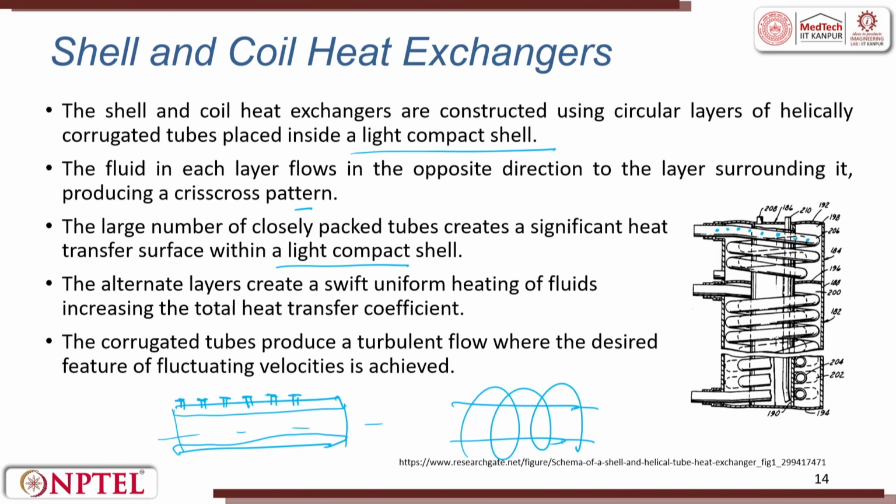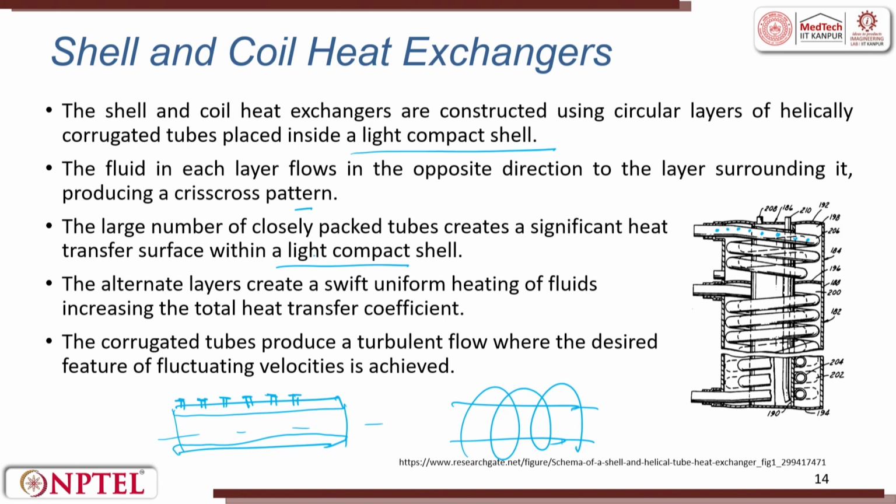But the size of the heat exchanger is also very important, because many a time these heat exchangers will be attached to a moving body. If it is for a static one, the size does not matter. But if it is placed inside an automobile, inside a car for AC, or inside a rocket which goes up, there the compaction is very important. So, light compact shells are very important. The alternate layers create a swift uniform heating of the fluid, increasing the total heat transfer coefficient.